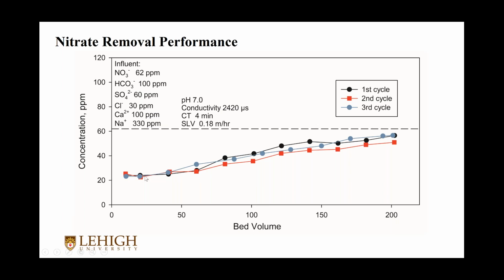This is very common for all the nitrate removal industry, because nitrate is very hard to be regenerated, especially for nitrate selective resin, because nitrate selective resin prefers nitrate very much. So during regeneration, it's going to be very difficult to completely regenerate. For the economical view, to completely regenerate the nitrate is not necessary, because as long as the nitrate is below the standard, we could just achieve our goal for nitrate removal.